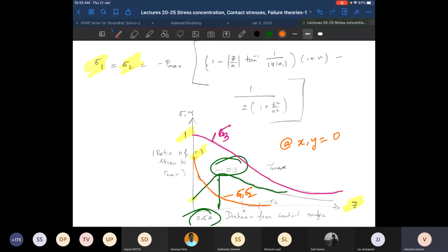The apparent friction coefficient means shear force divided by normal force, and in the majority of applications you do not try to extract more than 0.05 or 0.1. So the stresses are still predominantly coming from the normal force or normal stress.